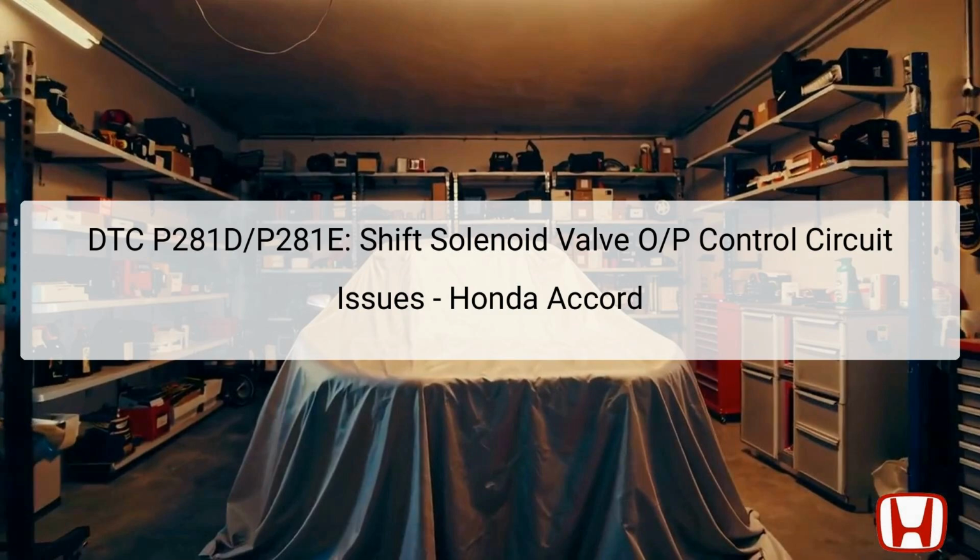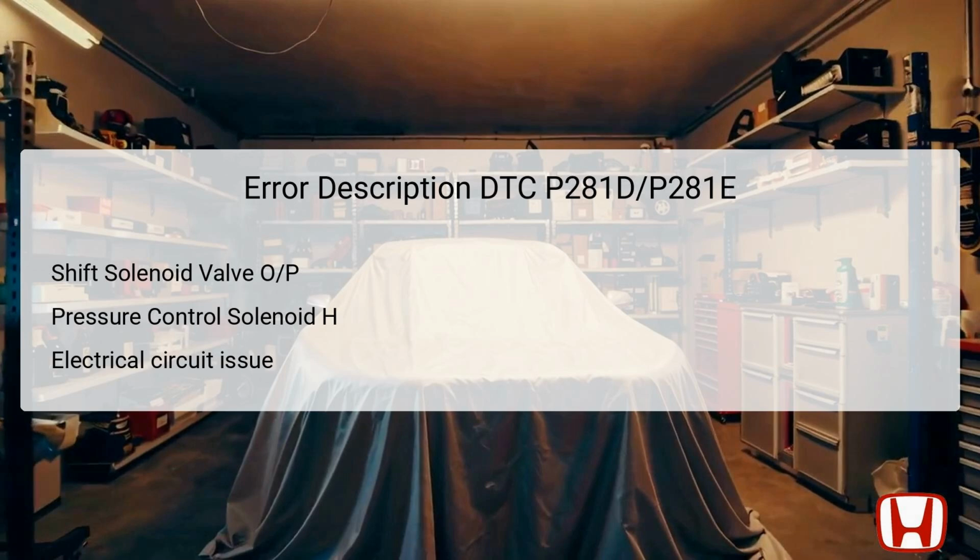The DTC P281D refers specifically to a low-voltage issue in the control circuit for the Shift Solenoid Valve Output, while P281E indicates a high-voltage issue in the same circuit. Both DTCs can significantly impact voltage delivery to the solenoid, affecting gear shifting and overall transmission performance. To effectively resolve these codes, a well-structured troubleshooting process must be followed, focusing on the electrical system associated with the solenoid. The errors represented by DTC P281D and P281E specifically point to faults in the Shift Solenoid Valve Output, particularly the Pressure Control Solenoid H.